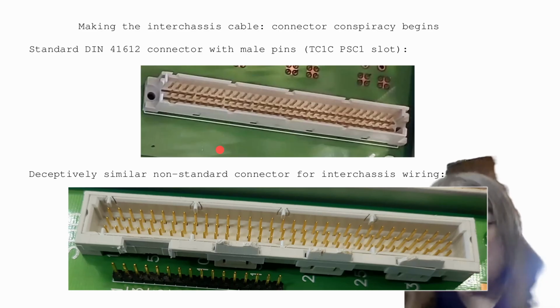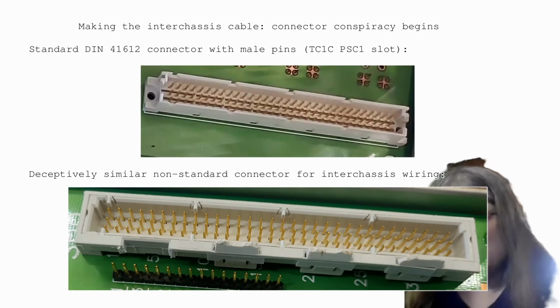So I thought it was the same DIN 41612 standard, and I thought, I'll just buy some DIN 41612 connectors from DigiKey, the full size C, because that's what it is. You got 3 rows by 32 pins, so it's 32 pins across 3 rows, 96 pins total. That's the most common size for DIN 41612 connectors. And so I thought, I'll just buy the Harting plugs from DigiKey and try to put them in. No joy, because